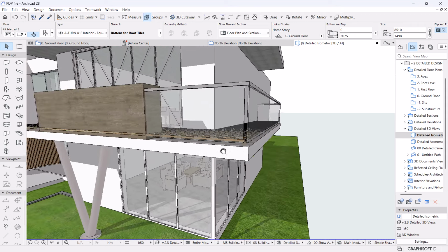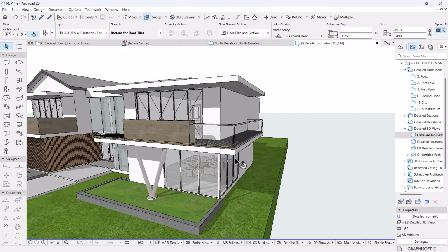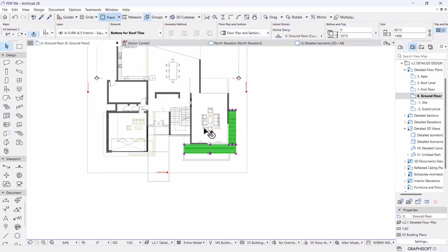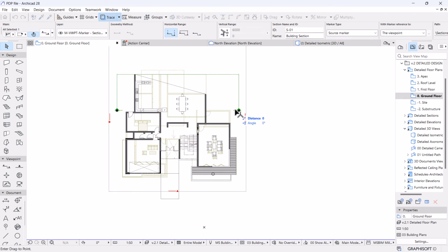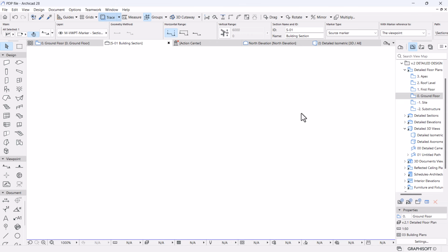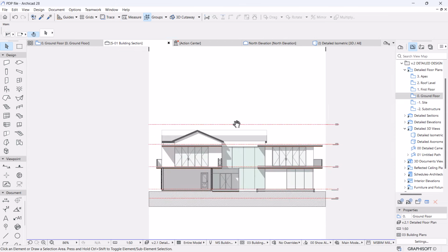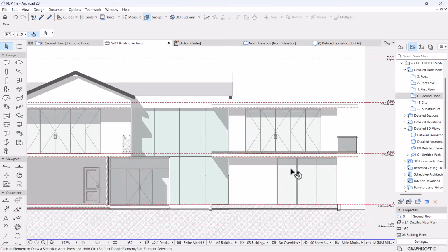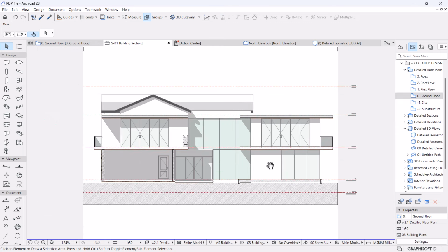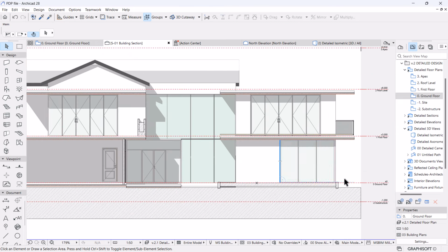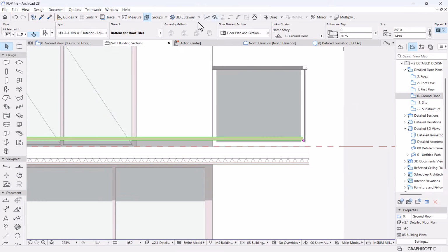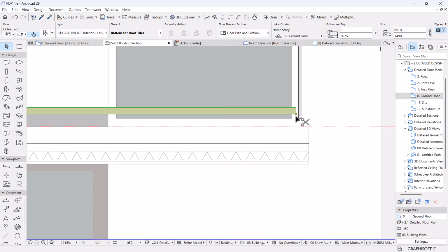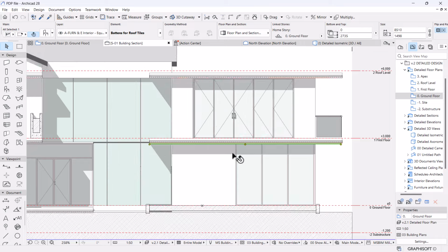the underside. I think this is where the introduction of sections will be now pivotal. So what I need to do is to take this section that I already placed and then move it somewhere here. Right click, open the section from here. It looks impressive already. This is what the presets of our sections on this template look like. It looks impressive. So I need to position this. Make sure the groups are suspended. Then I can position this to the underside of our slab like that.